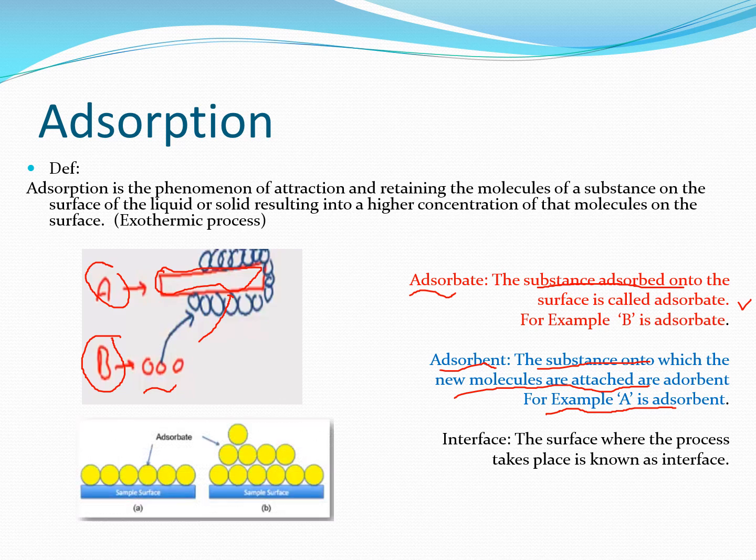Here you can also see another figure. We have unimolecular adsorption and multilayer adsorption, so I will discuss this a little bit. In unimolecular adsorption, you have only one layer of the adsorbate on the adsorbent, attached with the help of weak van der Waals forces. It's a physical bond, not a chemically reacted substance. It's a physical bond that can also be broken with the help of steam when we regenerate the entire column.